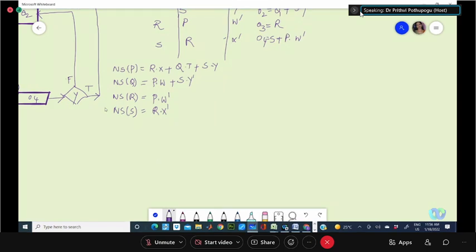We are not speaking of how many state variables we are taking. In your Mux method and traditional method, we had AB, the state variables, coming in. But here, the number of flip-flops needed is directly related to the number of states. Here, 4 states means we need 4 D flip-flops. Each flip-flop corresponds to 1 state.